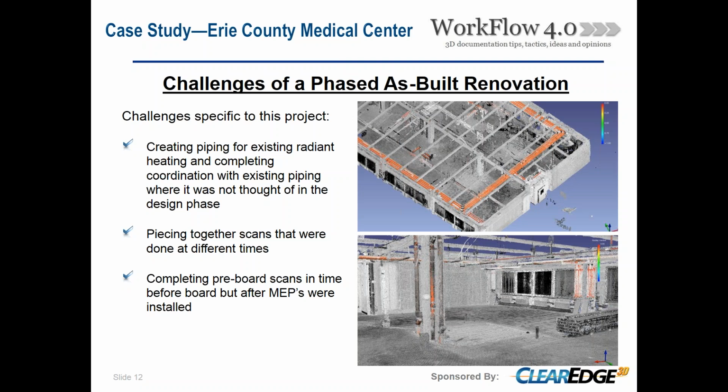And then the other thing that we did for this project was, as an example of what the scanner technology could do, we did some pre-board scans. This was quite a challenge with the expedited schedule. Because we had 2 shifts running on this project, it was tough to get in there when there was nobody working. So we ran into problems where there were people in the scans, but because this wasn't actually a required deliverable, it was just something to show them what we could do, it wasn't as huge of a deal. But if you're doing pre-board scans, it's highly recommended to do it when there's nobody around. It definitely compromised some of our scan data.